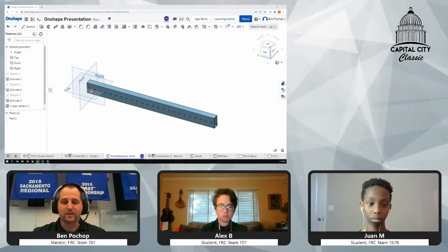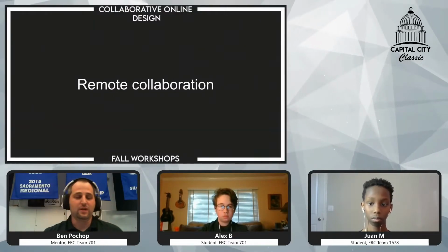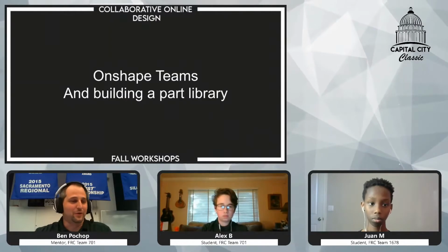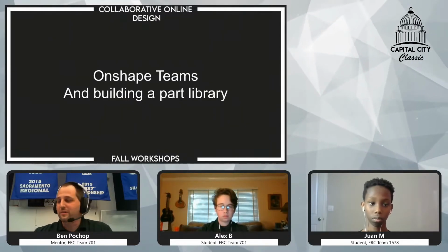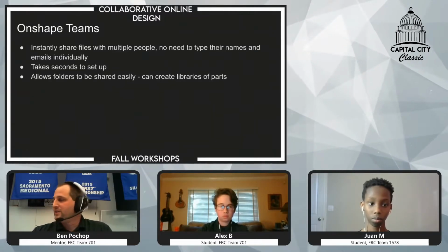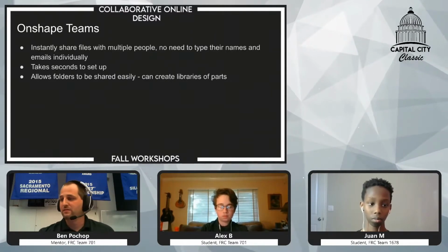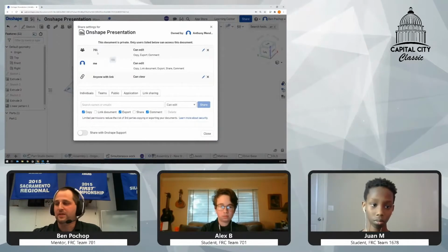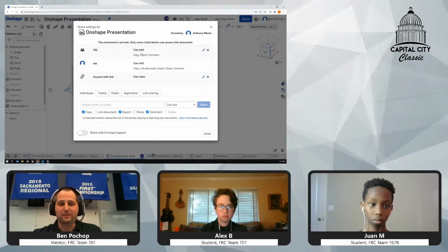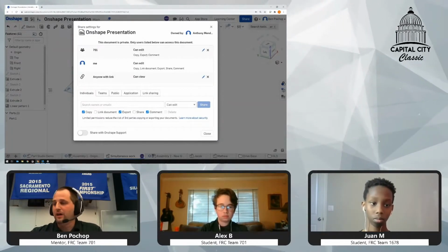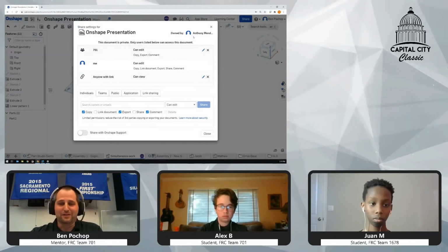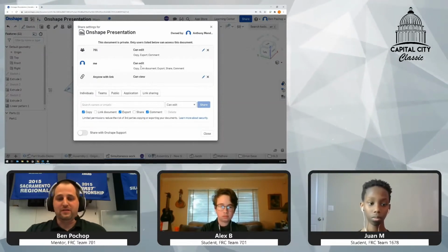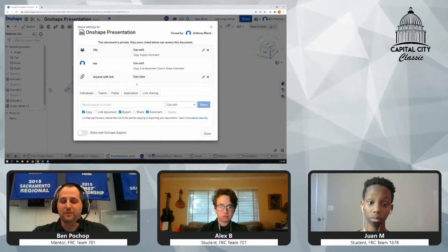So the next thing we're going to talk about is your Onshape teams. We had a step here where we were going to do a volunteer, but that didn't work out. So Onshape teams and building a part library. And you can see right here in my share settings, I've got Team 701. Everybody in that team can edit this document. I'm not actually the owner of this document. Someone else made it and I've added to it. So I can do all these different settings and then anybody with the link can view it.